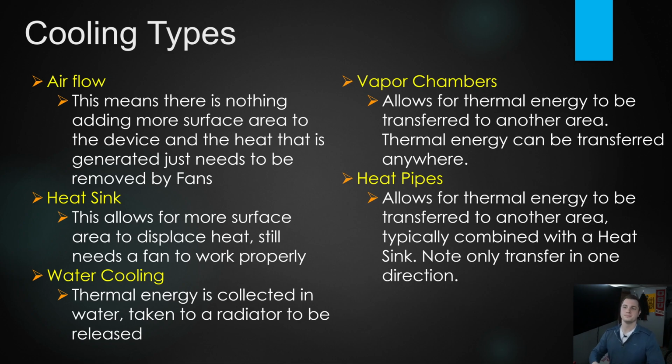So water cooling functions on a couple of different paradigms. One, it still needs airflow, it still needs fans, but it's going to function through a radiator. The reason why we use water cooling is because water does an excellent job of taking energy from one place to another. So what that water is going to do is take all the energy and heat from, say, the CPU, and then it's going to go up to the radiator and then out of the radiator when you have fans attached to that radiator forcing air through it. So this allows for more surface area. It also allows us to transfer that heat efficiently from one place to another.